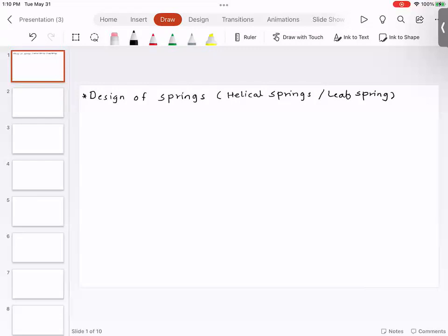side. So when we rotate the nut in one direction, say clockwise, then both the screws or both the bolts either come together or go apart. It totally depends upon in what orientation the threads are cut. In the case of turnbuckle, application is load transmission, not power.